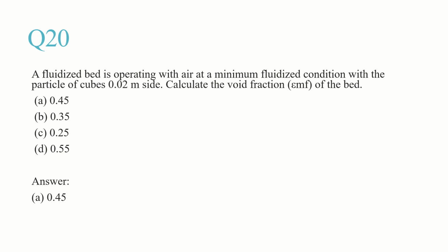We all know that at minimum fluidized condition the void fraction would be slightly more than that at the packed bed. Since 0.4 is the condition at the closed packing, it would be more than 0.4. So the answer to this is option A, that is 0.45.